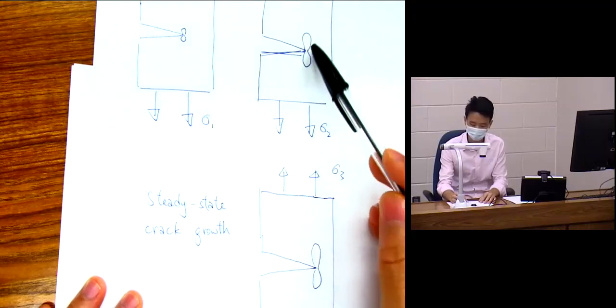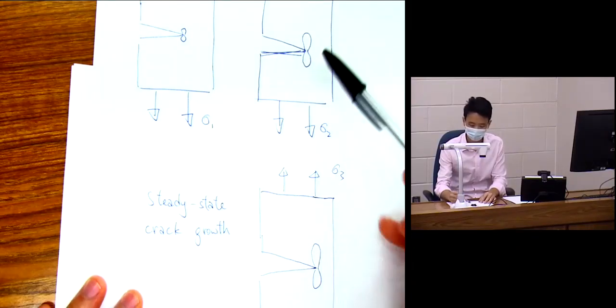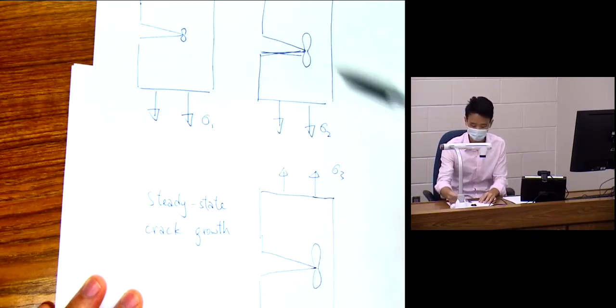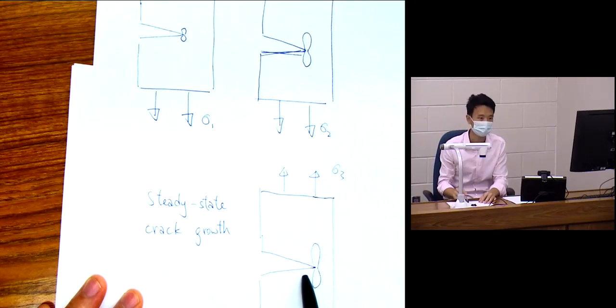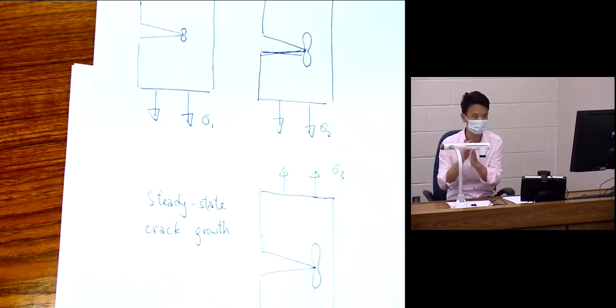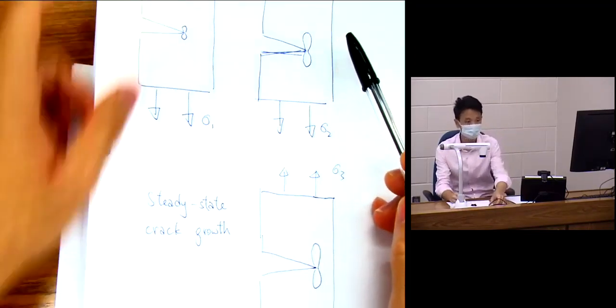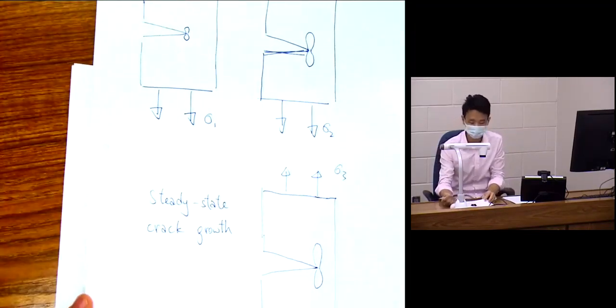This is already plastically deformed, so there's a yielding zone here. What is the amount of energy needed to make this crack increase by a unit length, right? And then you multiply by the width, that's unit area. So your crack advances, and it needs some energy to do it. The energy provided by the material to resist that crack advancement is the fracture energy.